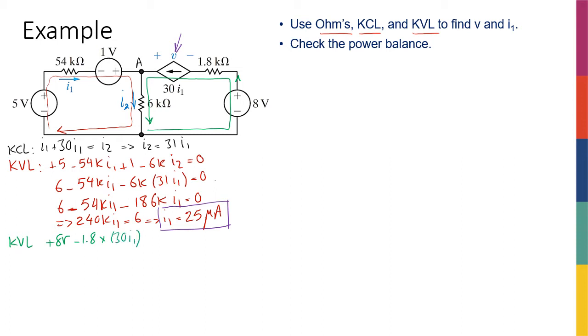And then I get to the current source. I need to write the voltage. Remember, this is one of the most common mistakes. Not a lot of you do it, but it's very annoying because it does not mean anything. So when you're writing KVL, each of these terms that we are writing is a voltage, right? So here's an 8 volt, right? This term is the voltage across the resistor. It's an RI.